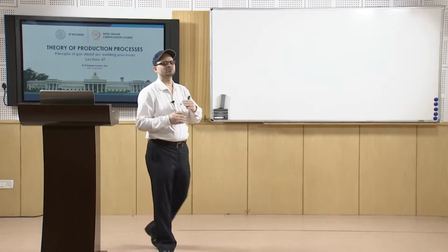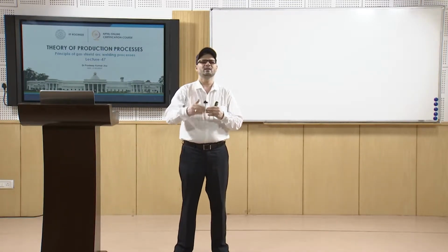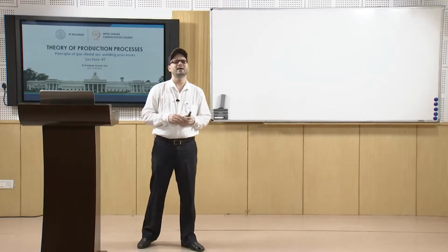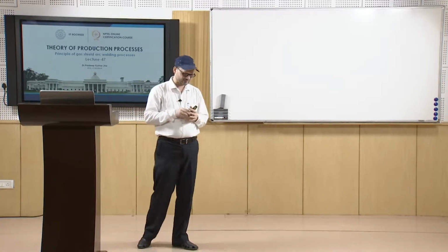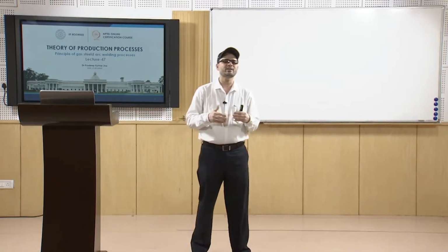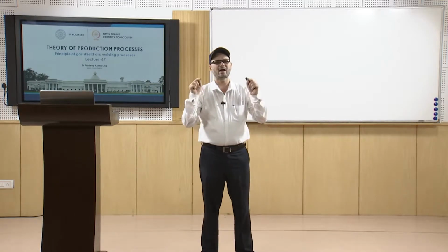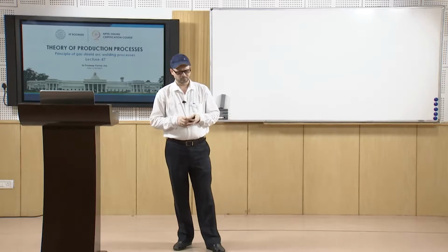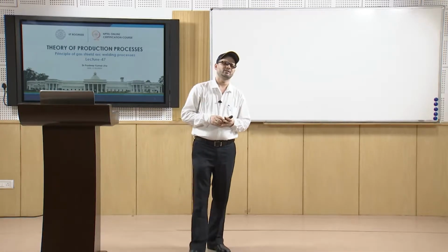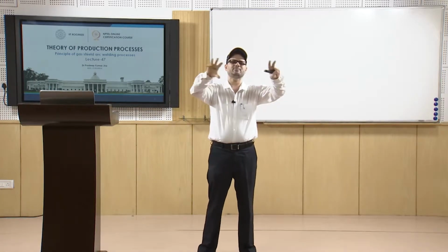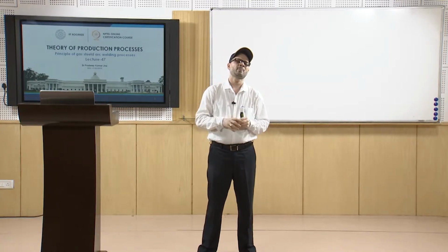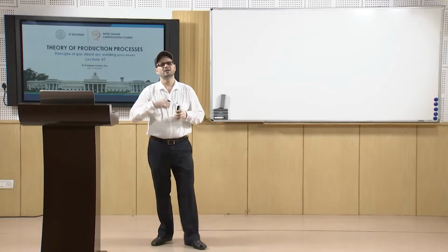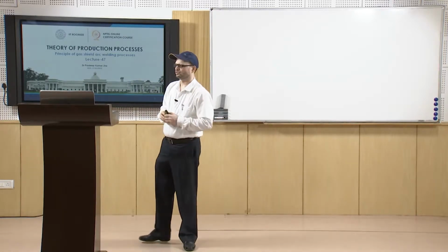The gases which were used then, and even now, are mostly helium and argon. Since these gases are non-reactive, they are passed at the point of the welding, in the weld metal zone. That covers that area, so that there is no atmospheric contamination and the welding process goes on.